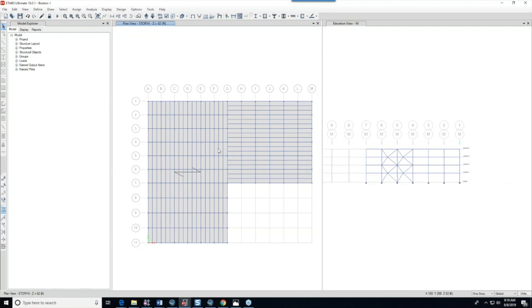We know that if you have a rigid diaphragm, the program knows the center of the diaphragm and the center of mass, and it can apply the total force on one point because the diaphragm is rigid. But if it's semi-rigid, you want to distribute the loads, and it's very convenient to do it with seismic forces because we know what the mass is of all the joints.